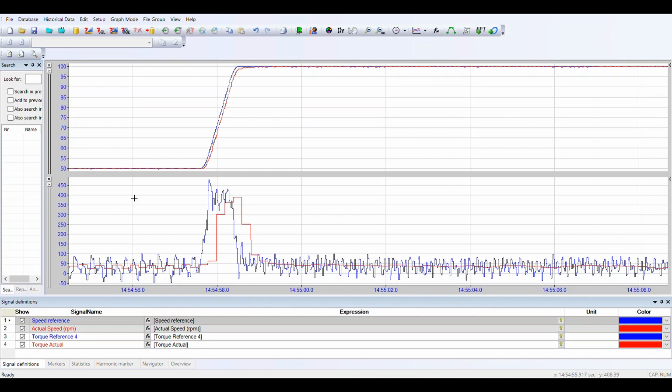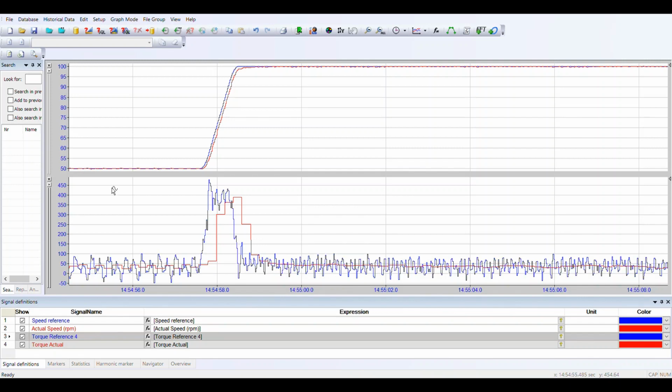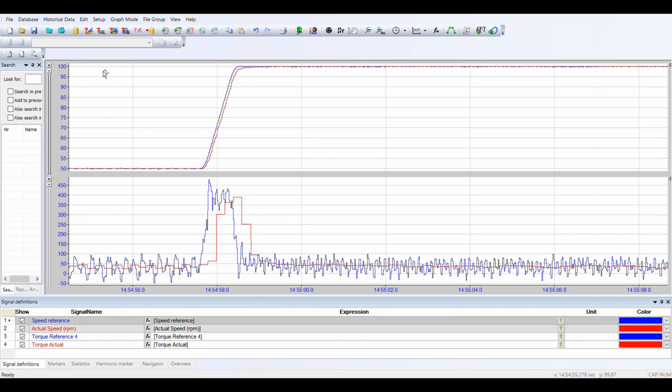That generates an additional torque reference 2, which gets summed up, and the final reference goes on as torque reference 4, and that reference is sent to the vector control block, which passes the switching signals to the inverter, which runs the motor. And finally, you get the actual torque. This is just to verify that my actual is meeting my reference, and the speed reference is meeting my actual. And because this is in speed control mode, the priority is to meet the speed reference and speed actual.